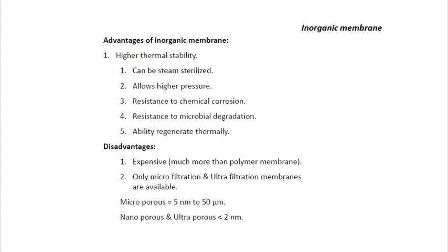There are several advantages of using inorganic membranes. First is thermal stability. It can be steam sterilized, which means inorganic membranes can be used in the food industry and the biotechnological industry, where bacteria will grow with time on the surface and you have to remove that bacteria. For that you have to use steam sterilization, which is not possible with an organic membrane, because an organic membrane cannot sustain very high temperatures, but an inorganic membrane can.